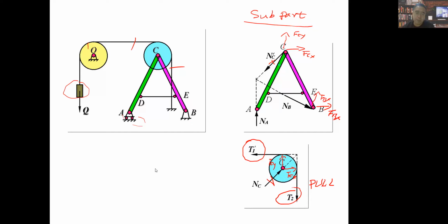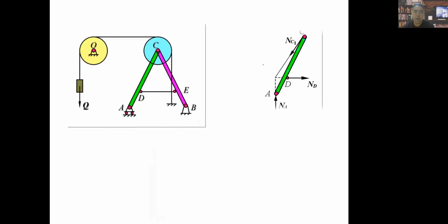So in this chapter, we should know how to do the force analysis correctly. This time we only select this AC as the object to be studied. So we should draw this one out of this whole system. We should remove the constraint here, cut this rope here, and remove this constraint here, right?